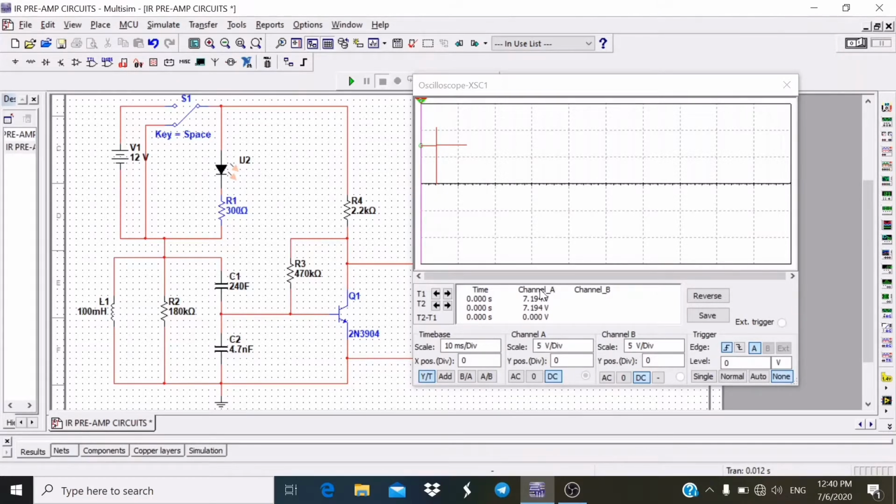It sends the IR signal and feeds it into the 30 kHz tuned circuit by L1, C1, and C2, which is slightly damped by R1. The resulting frequency selected low noise output of the tuned circuit is tapped off at the C1 and C2 junction and amplified by Q1.